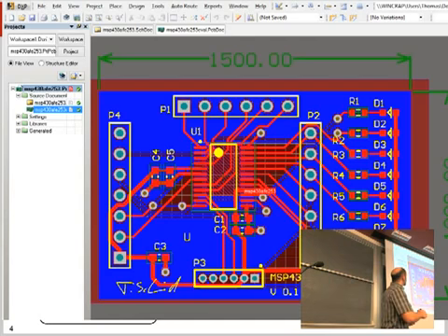So this is basically taking the schematics you have seen before, putting it into the printed circuit board editor, and then start laying it out, making the traces from the different parts to each other, putting the capacitors where you really want to have them, putting the connectors where they make sense, putting the LEDs in a nice row and not just straying them all over the place or having them in a circle around it, or however you want to align them for your physical design. Once you have this in your PCB editor, you go to the next step.